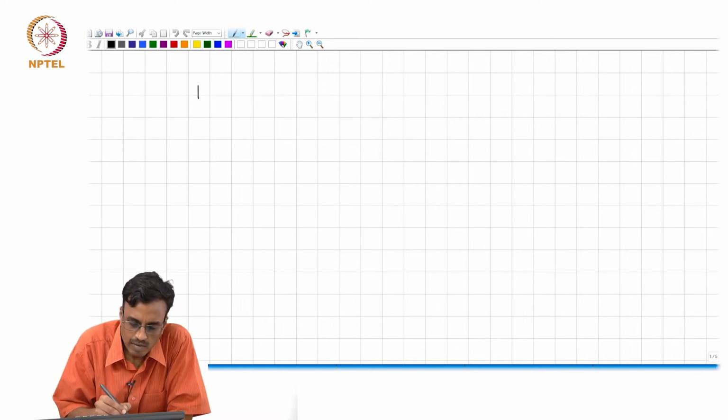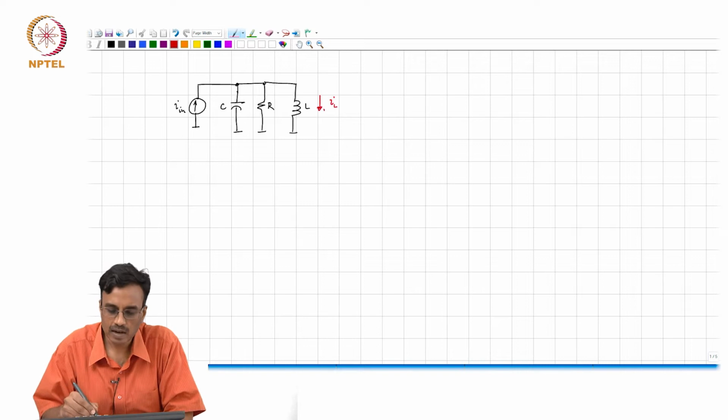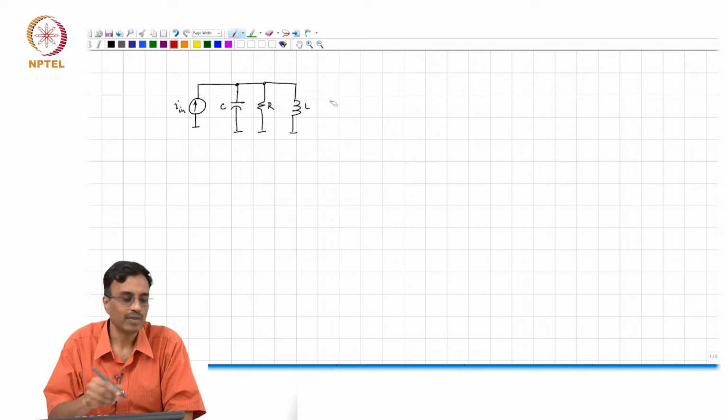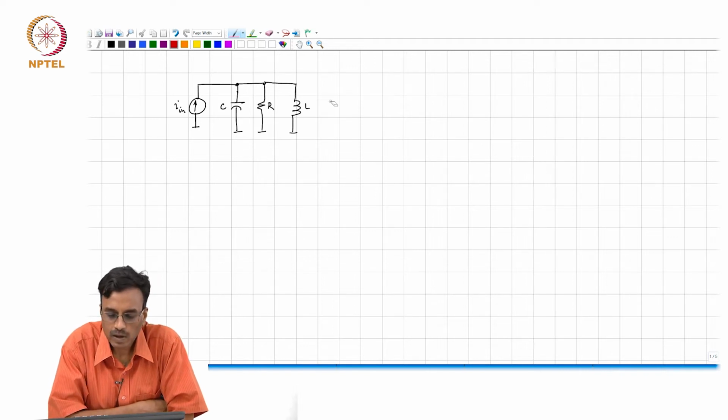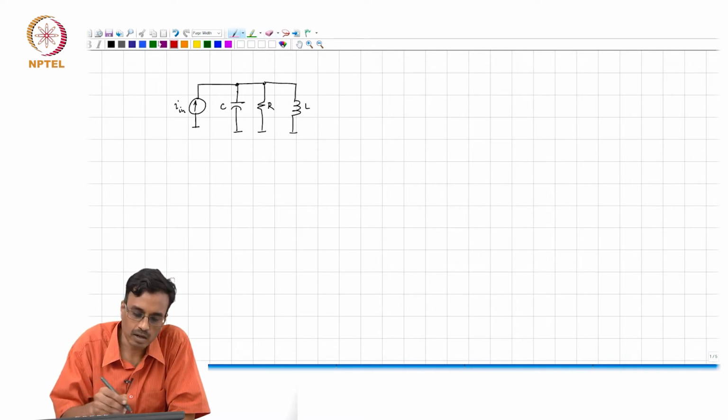If you remember, we started off with our quest for realizing a filter using this RLC circuit, and the low pass output corresponded to the inductor current I. Then we went about trying to realize the inductor using op amps, R and C. Yet another way exists, if we do not want to use the inductor here.